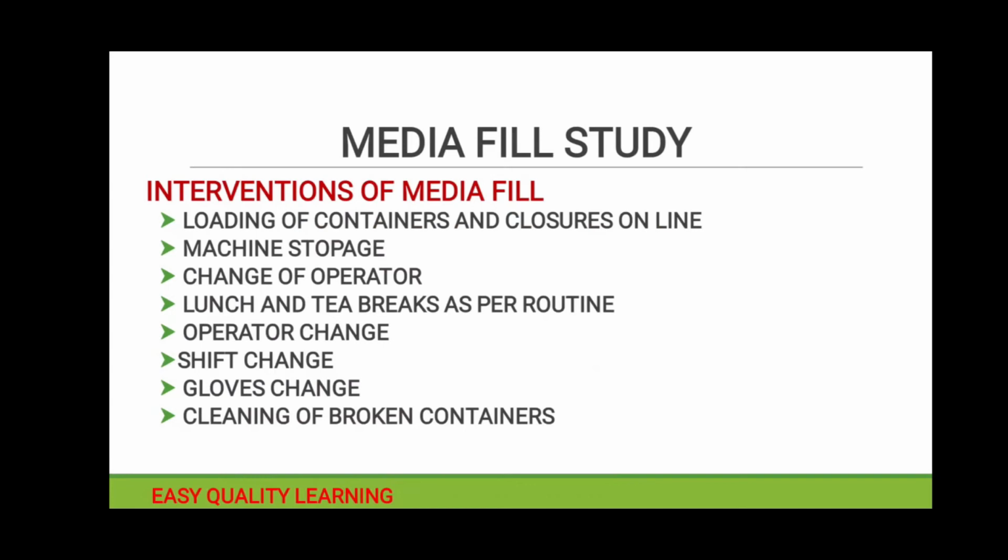Then gloves change. People generally have an SOP that after a certain interval we need to change our hand gloves. If there is such a practice, the same shall be simulated during your media fill activities. Cleaning of broken containers. Whenever our line runs, there is a possibility that a few glass containers will break, and there will be an intervention where we need to stop the machine.